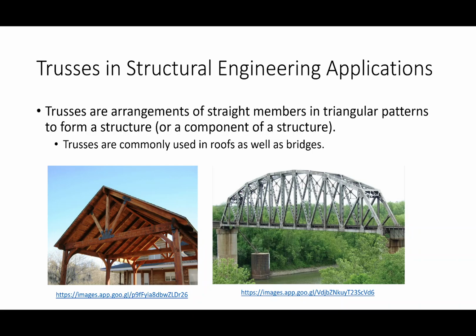Strength refers to how much force a given system can withstand before the system fails, before it falls down and kills somebody. That's what strength is. Stiffness is the relationship between applied forces and resulting displacements. Now, are strength and stiffness related? Yeah, for the most part they are, but they're not the same thing.